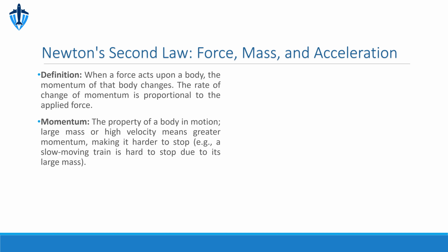Next, let's delve into the single fixed pulley. This type of pulley functions much like a first-class lever, where both the effort arm and the resistance arm are equal to the radius of the pulley. Because of this equal arm configuration, a single fixed pulley provides a mechanical advantage of 1. This means the effort applied to the rope must be equal to the weight of the object being lifted. Therefore, its most significant advantage isn't to reduce the force, but rather to change the direction of the force, allowing you to pull downwards to lift an object upwards. This figure visually represents this setup.